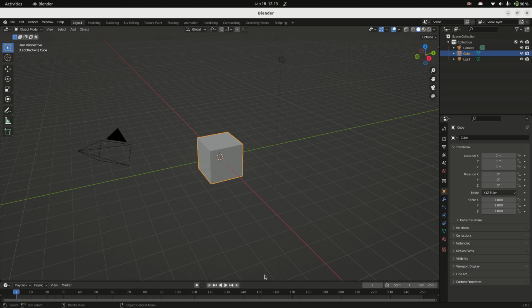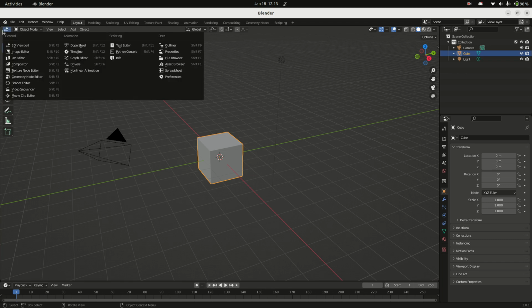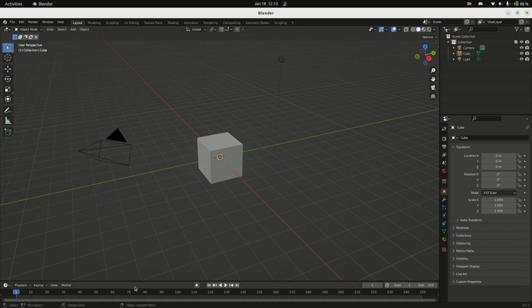And you can see there's a slight difference in highlighting between when my mouse is over this 3D view window, this editor 3D viewport, or this timeline viewport down here. Whichever one my mouse is over is going to get any kind of keyboard hotkey input. Now the default is left click selects.